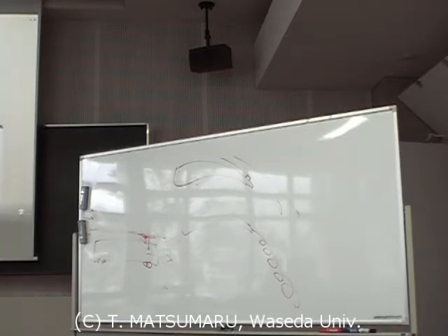So let's start with why we need vortex generators and work our way back to how they work from there. Let's say you have a flow traveling along a flat plane, like this. At any point on that surface, the flow has to be stationary. It's a basic fluid law. So what you end up with is a free stream flow velocity, a stationary flow velocity, and some sort of profile going in between. So the flow here is slower than there. This is known as a boundary layer, and is where a bunch of turbulent mixing occurs, and it's got several different zones. That's not important.